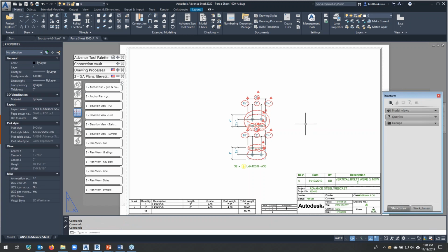So I just wanted to make sure that you could witness that when you do a revision of a model, the drawing notification will be tracked, and when you update that drawing and add a revision to it, the clouds will be automatically added to your drawing for you. And so that should be a huge time saver for those of you that work in that space and you're revising drawings on a regular basis.